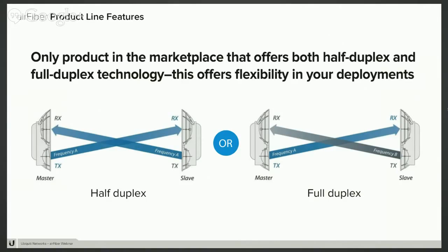As I mentioned, we support full duplex and half duplex as well. Here are a couple of typical configurations. Typically in a half duplex setup, you would see that we'd be using the same frequency for receive and transmit. And typically on a full duplex radio, you'd be using different frequencies. There's actually no requirement for that, as both modes can be supported whether you're in full duplex or half duplex, but this is typically what you see.